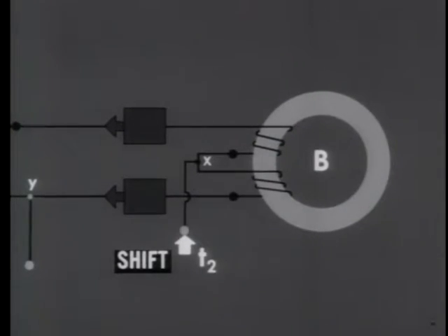The upper branch current comes out on the non-dot side of its half of the split winding. The lower branch comes out on the dot side of its half of the winding. And both of them move along to the diodes.